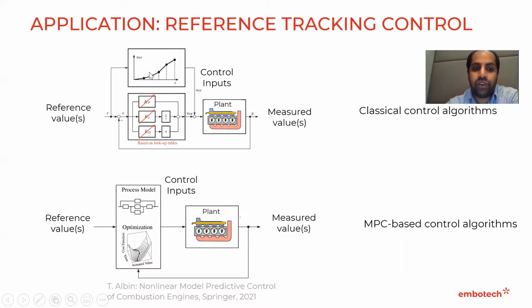So you have some feed forward control action, and you have some feedback action, for example, a PID controller. If you have a nonlinear system that you want to control, then typically one way to deal with the nonlinearity is to use lookup tables, and then your parameters Kp, Ki, Kd become operating point dependent, and the same holds true for the feed forward control. So you have, for example, reference point dependent feed forward actions.